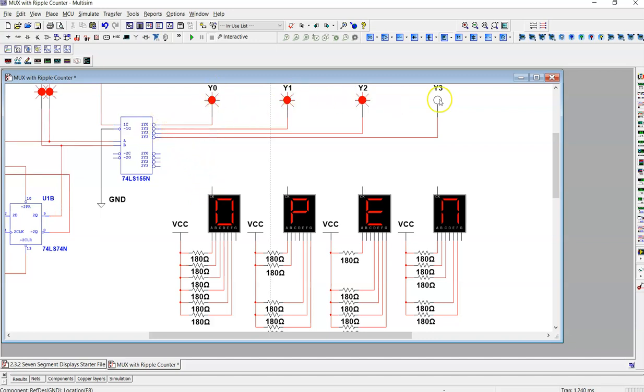So I just have some probes just to see which output is currently the output that's going. And you notice that we've got 3 1s or 3 lights on and a 0. It is the 0 that is going to power. It's the ground. Because this being a common cathode, it's the ground that we need here, not the power. We've already got the VCC, the 5-volt power coming here on this side of the LED, so we need the ground on this side.